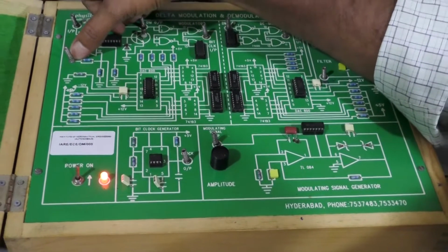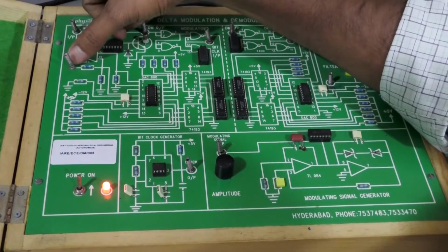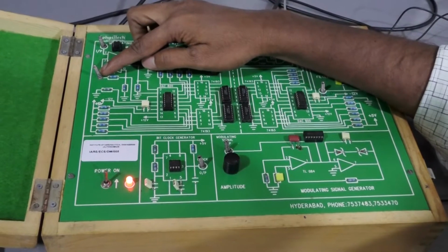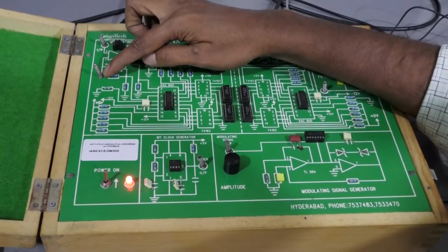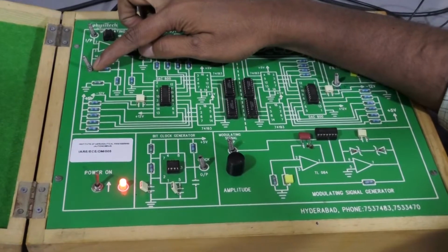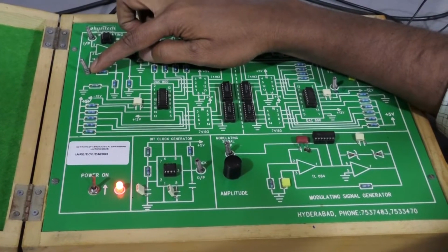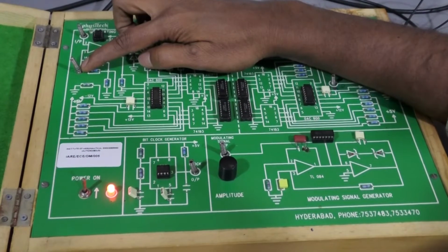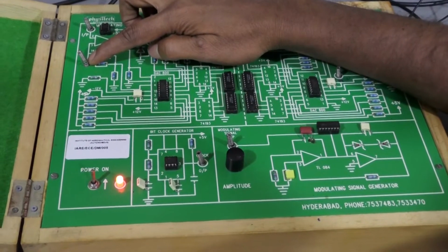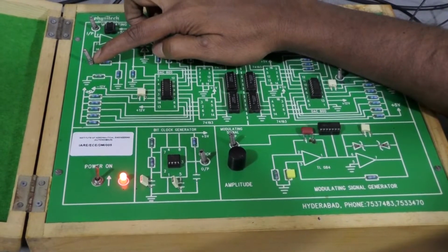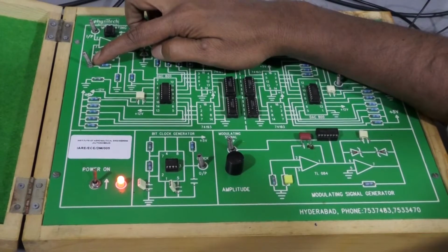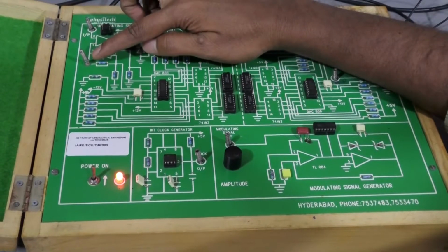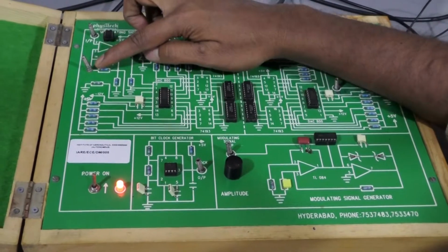If the previous sample is less than the present sample, the delta, which means the staircase signal, is increased by 1. If the previous sample is greater than the present sample, the staircase signal from the delta modulator is decreased by 1, which means the previous sample and present sample give the ones and zeros. If the step is increased by 1, the data 1 is transmitted. If the step is decreased by 1, the data 0 is transmitted.